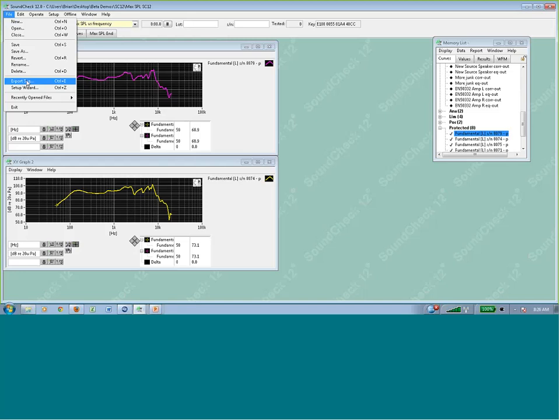So for example, if you had a DAT file that was being recalled by the sequence and you had a stimulus WAV file, by using the export operation, it will take the sequence file as well as those two files and bring them over into a single location, and it will set their file paths to relative so that now you have a sequence that can be easily moved from one place to another.